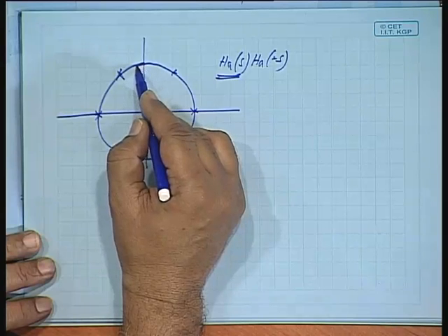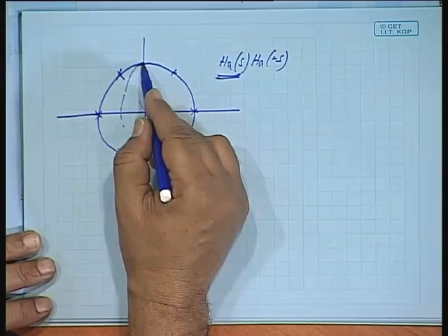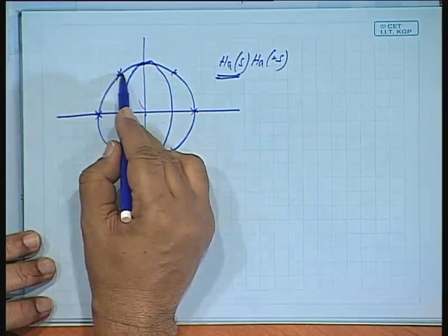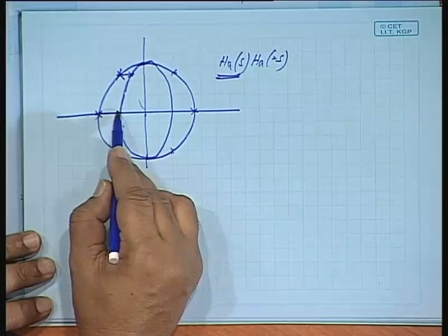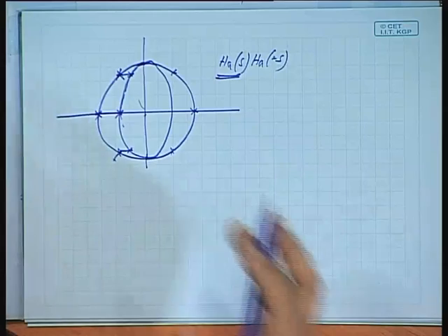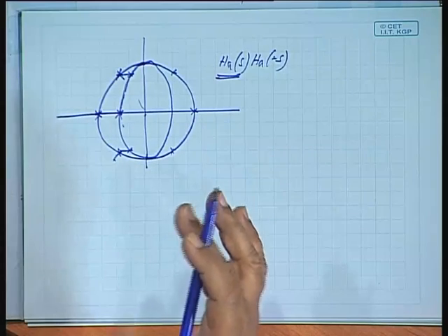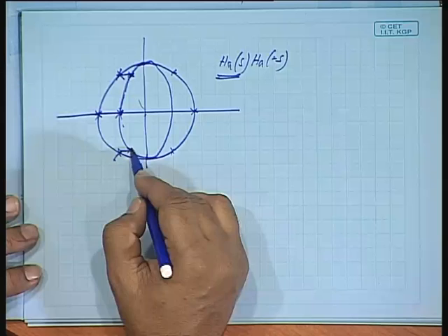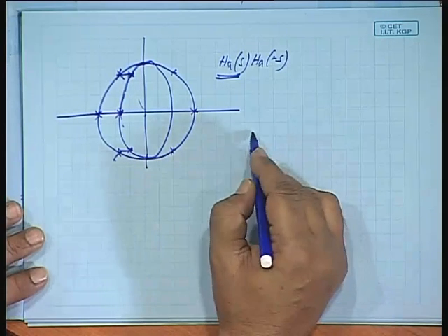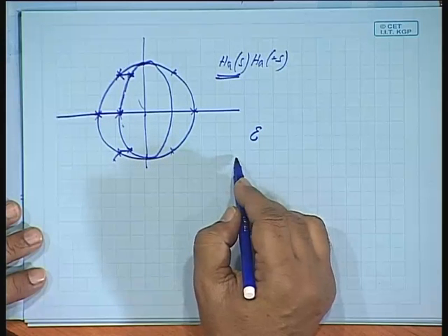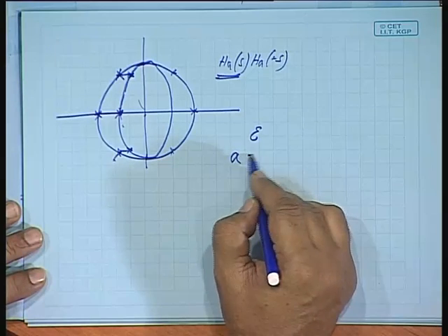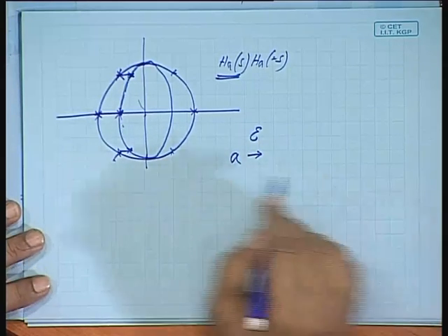There is a relationship: the ellipse that you get for the Chebyshev filter will be like this, and the real parts shift by a factor and the imaginary parts remain intact. You just squeeze the real parts, then you know the locations of these. Then it is very simple. So, given epsilon, you can calculate a factor A, which you can evaluate from epsilon.